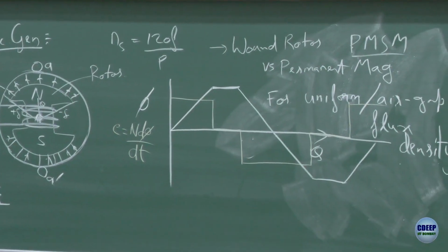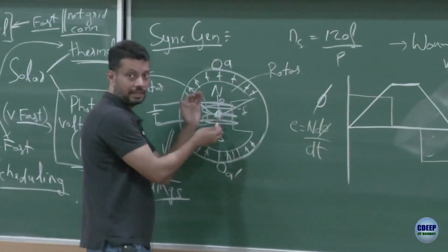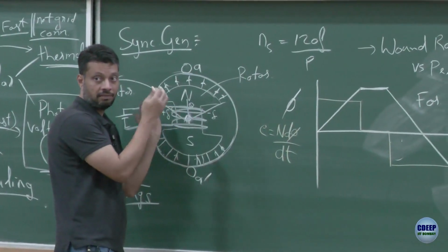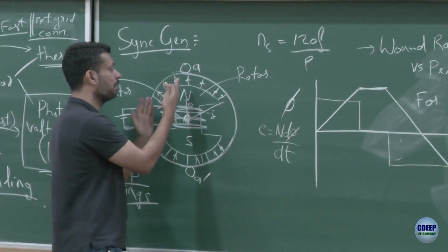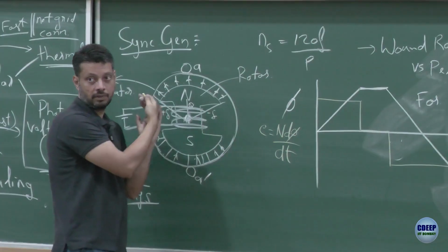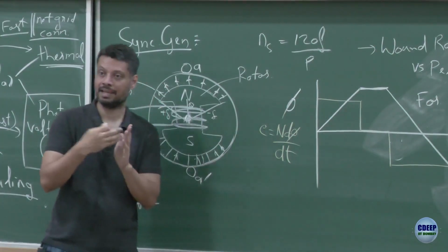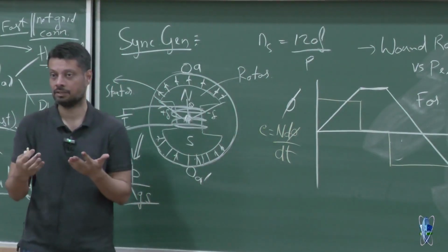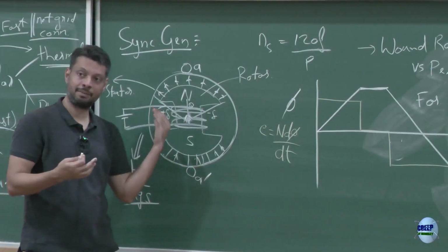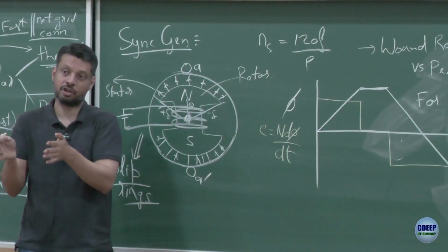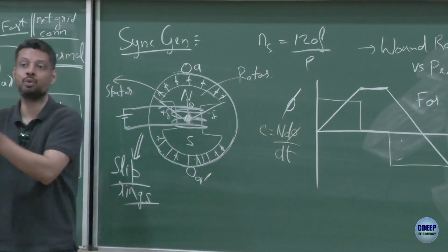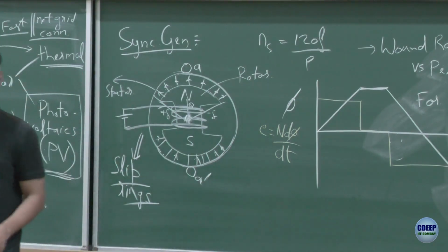Is that okay? For every theta rotation, you have n number of lines coming in from right to left, so your flux is increasing by n. If you do 2 theta rotation, you have 2n lines coming in of equal strength. So your flux increases proportional to 2n, which is proportional to theta.